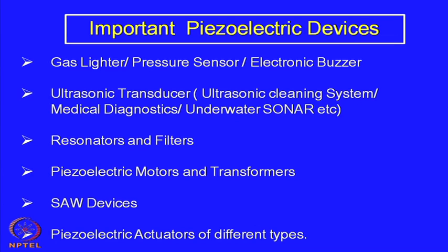If it is a solid-liquid interface, then the transmission becomes difficult, because at the interface you have what we call a big impedance, acoustic impedance. Acoustic impedance gets generated when the ultrasonic wave is generated within a solid medium and then moves to a liquid medium. So, there the impedance matching is very important.